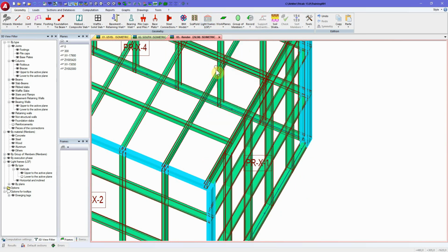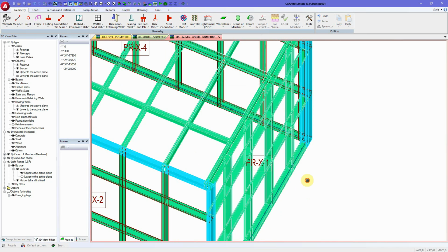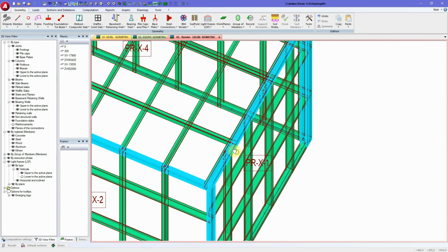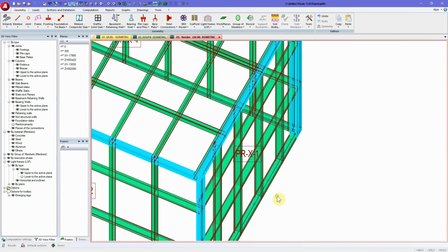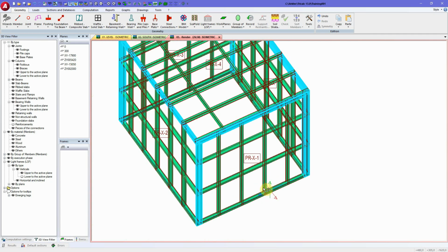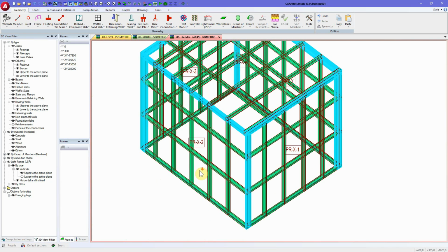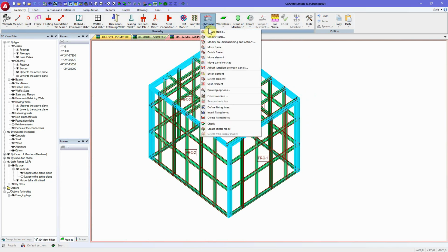If we change the connection type, let's say for this one, connect this panel to this one, then in that case, it will automatically recognize the connection as terminated. You can at this time create a structural model if you'd like. Here, create the structural model and test it. So this will be a quick way to test your structure, if it is doable, if it is viable, if you can test it correctly.